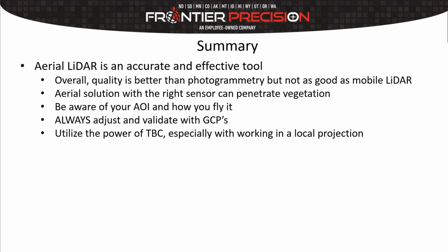If you have an aerial solution, with the right sensor, you can definitely penetrate vegetation, which we saw in one of the slides. A couple of things: just be aware of your area of interest and how you fly it. We had that issue going around the curves where we're missing some data, and then always adjust and validate your flight with ground control.